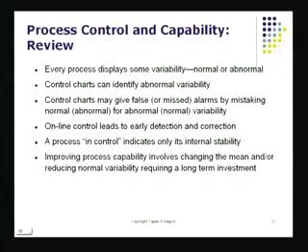In order for us to get an assessment of the capability of the process, that is how good the process is in meeting customer requirements, we have to come up with an index that is called process capability. And there are a couple of ways to measure that. One is, of course, you worry just about the spread of the process. You don't worry about the centrality of the process. In that case, you'd be using this quantity called CP. If you use CP, you end up with a simple formula.